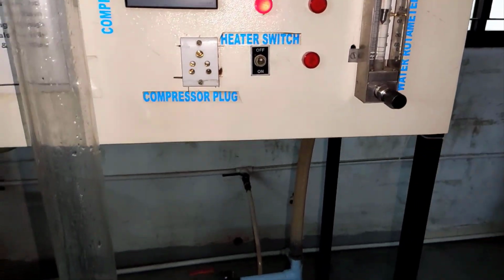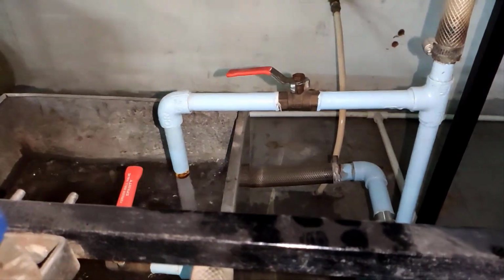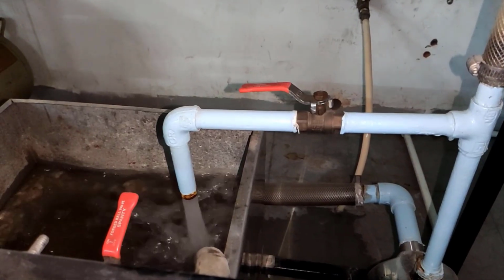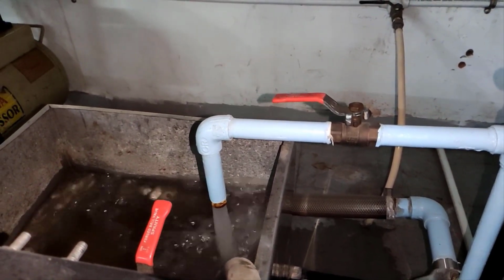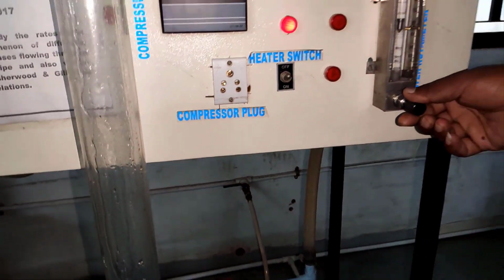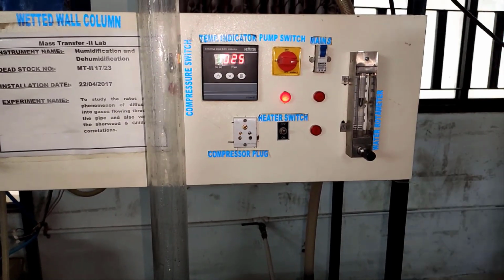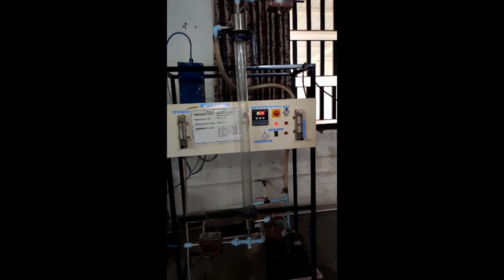We will try to maintain the water flow rate. Now this is the bypass valve. As you can see, it is fully open right now, so most of the water is being bypassed through this. Okay, and now we will try to manage the water flow rate by adjusting the rotameter.